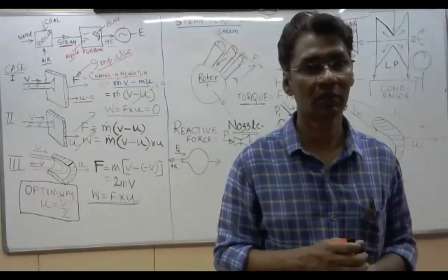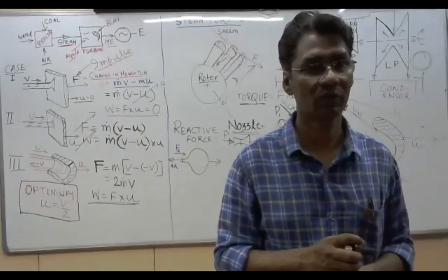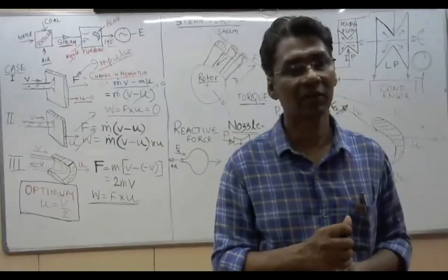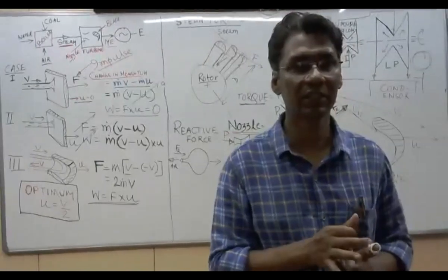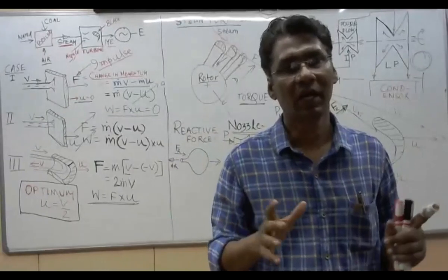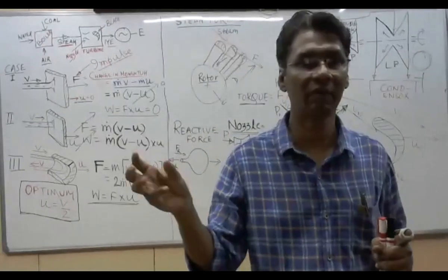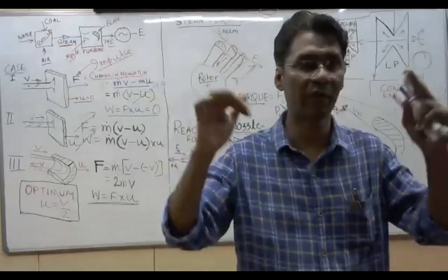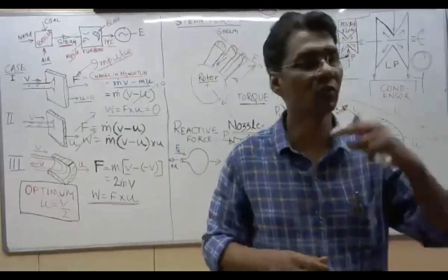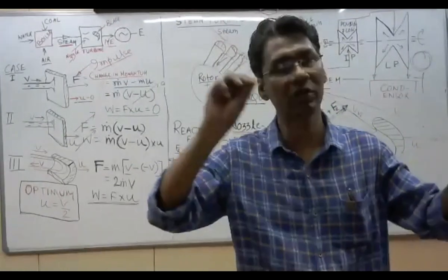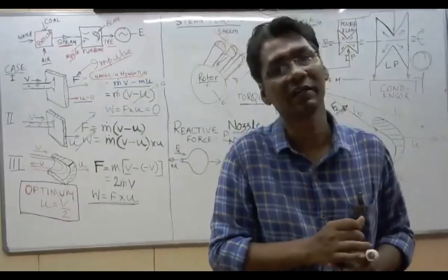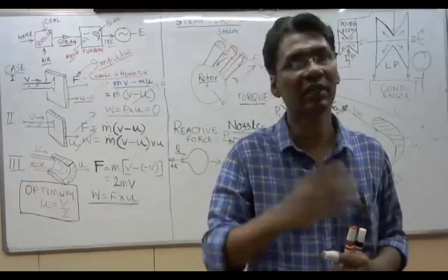Why are these control valves controlled, and using which type of control system? The turbine is controlled by oil pressure through the turbine governing system. That is a schematic of the governing system, and it depends upon the steam amount, frequency, and a lot of input parameters. It is processed by microprocessor, and a signal is generated to produce oil pressure. That oil pressure controls the control valve. This is in short. Actually, this governing system is not so easy, and by the governing system we control the turbine speed.